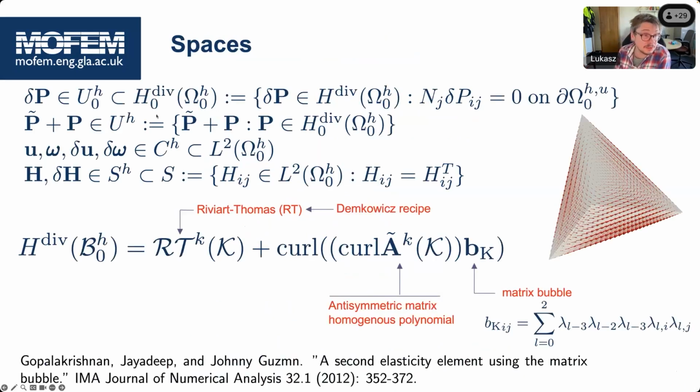So what we do, we approximate the Piola-Kirchhoff stress in H-div and the variance in H-div. We approximate the stretches, displacement, rotations, and variance of the displacement and rotation in L2. And we approximate on the mesh the logarithm of the stretches. So for any set, that system gives us that if you choose degrees of freedom on the mesh randomly, you will always get finite energy, zero or positive energy.